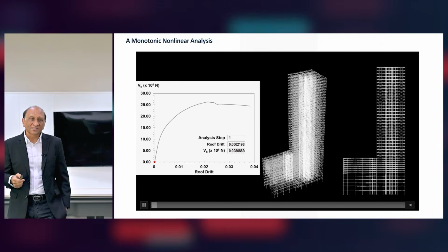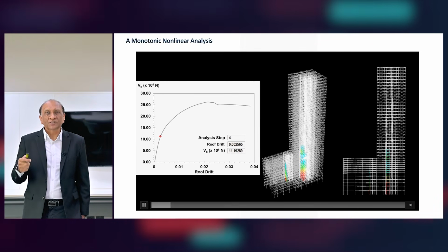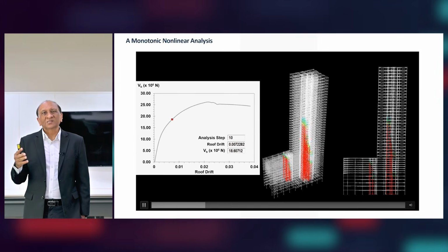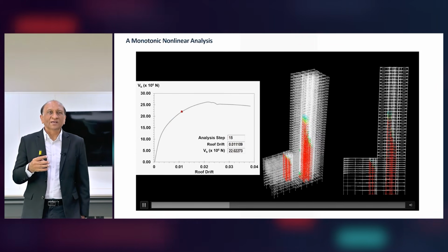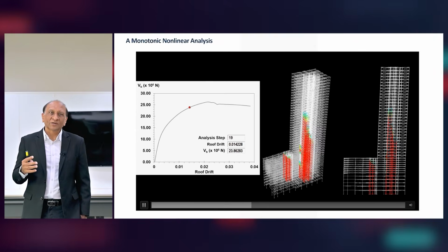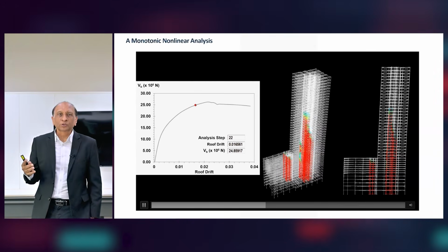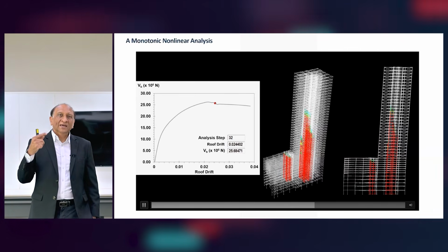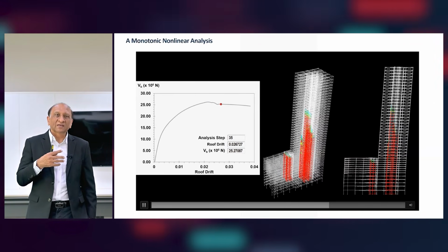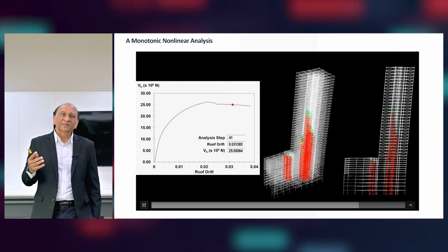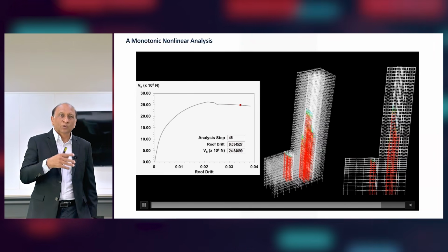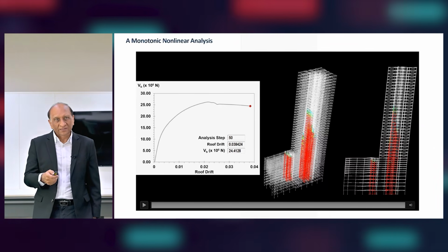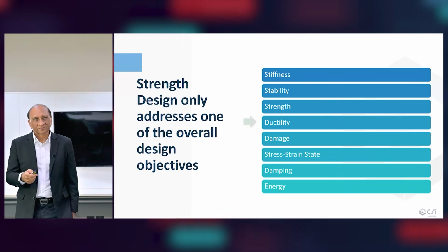If you use the same approach in a large structure, then you can determine the stress state, failure state, and damage state in a structure by going through the pushover curve while monitoring the curvature, strain, and stresses. That means it can give you a full picture of the structure response as the load progresses from zero to the maximum. And that's the benefit that we have talked about.